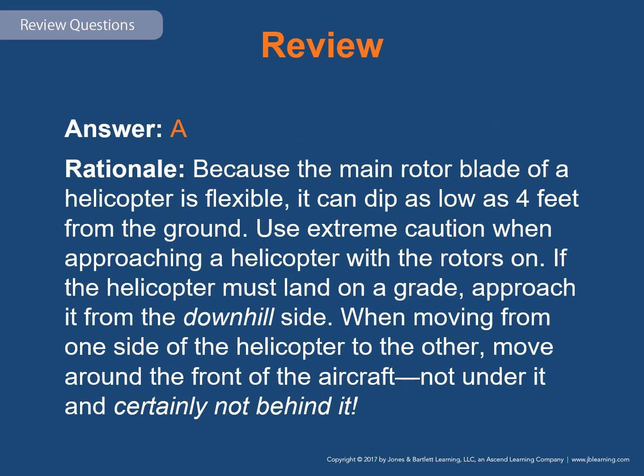It is A. Because the main rotor blade of a helicopter is flexible, it can dip as low as 4 feet from the ground. So use extreme caution when approaching a helicopter with the rotors on, and you will not be able to see it coming at you if it's low like that. It's moving at a speed that causes an optical illusion, and you can't see it. You don't realize it's that low. So use extreme caution when approaching a helicopter with rotors on.